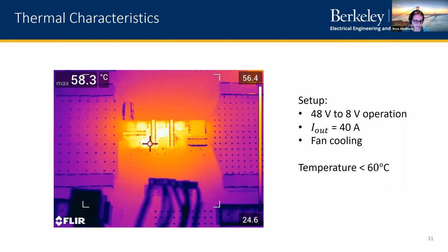And what's interesting is some industry manufacturers of similar types of converters, when they test the efficiency, they actually do pulse testing. So they turn it on and measure the efficiency and then turn it off. So it hasn't been heating the whole time as you've been increasing the power. That's a measurement style we're maybe looking to try to have more comparative data. But I think that would only get us to higher efficiency numbers because we are allowing the board to heat for a long time as we step up the power.